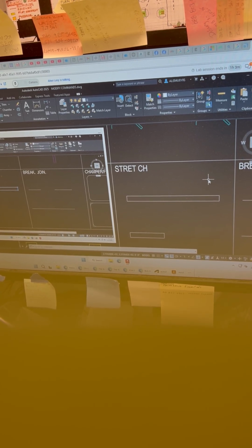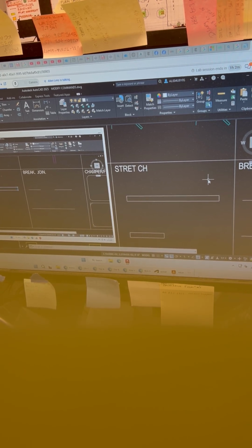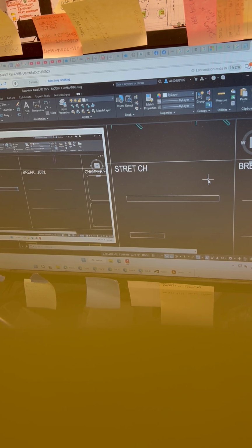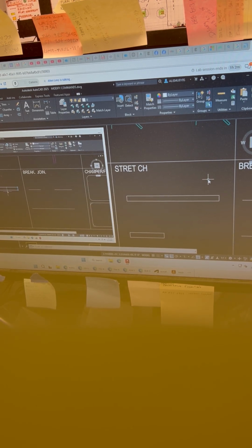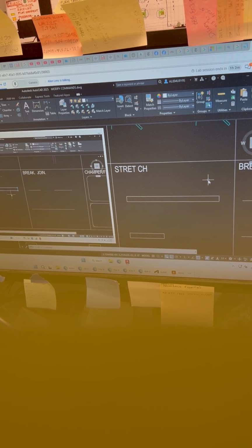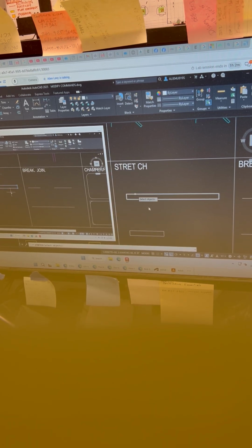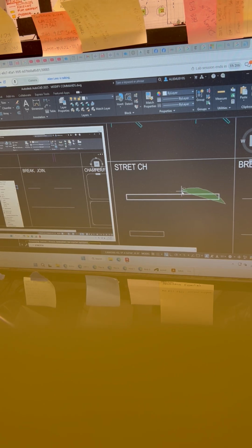Now, the stretch command is an unusual command in the sense of how the elements are selected. The elements for a stretch command are selected by using a crossing window. And that's the only way. I have this element selected right now. Now I could probably do something with the stretch command, but the main order of operations is you start the command first, and then you use a crossing window to not select the entire object, you select a portion of the object. All right, so let me deselect this object.